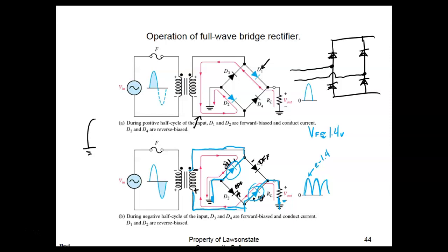So a printed circuit board, you can't cross their conductors. They're basically uninsulated, so you can't cross them. So they're concerned with how do we get this conductor from point A to point B without crossing other conductors. So the components on a printed circuit board are not going to be laid out like the components on the schematic. To help you do that, they're going to put these part numbers, those designators, on there. If they don't do that, then you get very upset.